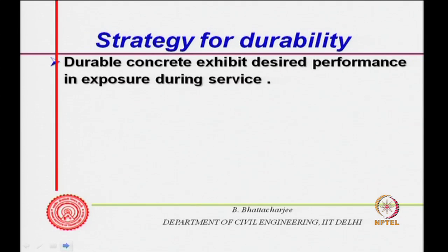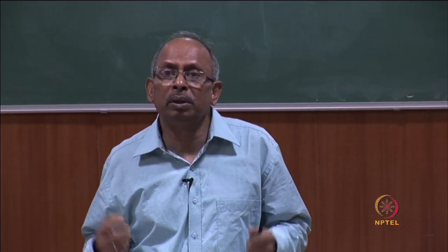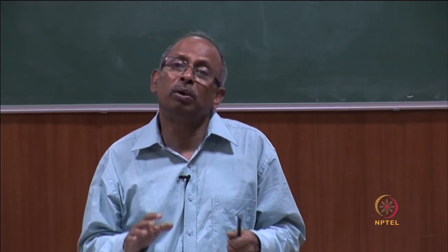But we have to have a strategy for durability, and we have had one in place over the years, which is improving. A good lot of it is right now prescriptive. We will look into the prescriptive situation of the IS code, but let us see what the possible strategies are. We have an understanding of the difficulties in quantitatively estimating the service life of concrete, because it depends on so many factors, the environment, the materials, and also our lack of understanding of a complex material like concrete, which is not a single compound but many compounds: how it will react, which compound will react under what situation. All these complexities are there.